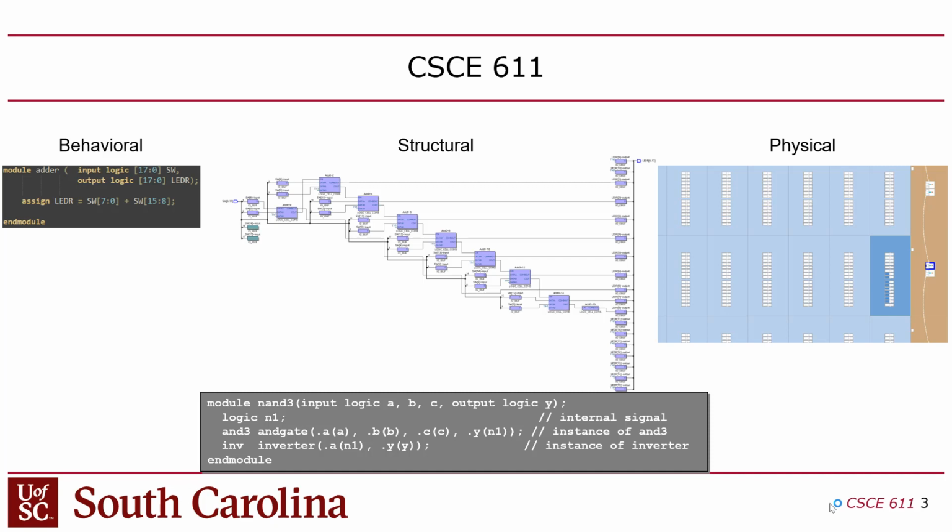And then the structural design, now this one's a little confusing because in the SystemVerilog, you synthesize it with a compiler. So when you compile it, it gets converted into a structural description, into a schematic automatically for you. However, you can also design schematics in Verilog as well. So it depends on how abstract your SystemVerilog could be. Very abstract, where it's like a big logic equation, and then you're expecting the synthesizer to convert that equation into a sea of gates connected with wires.